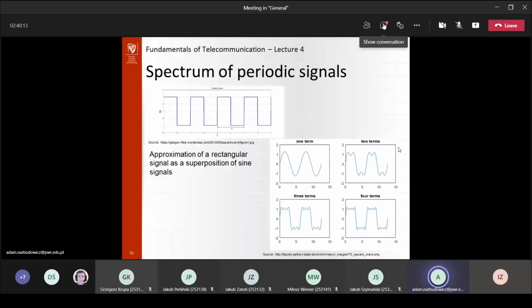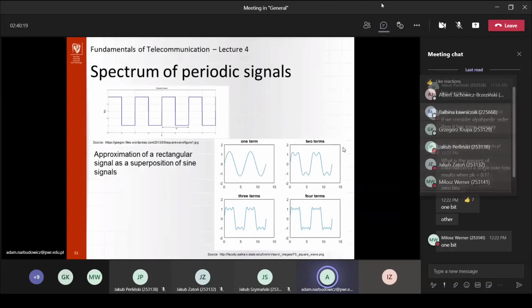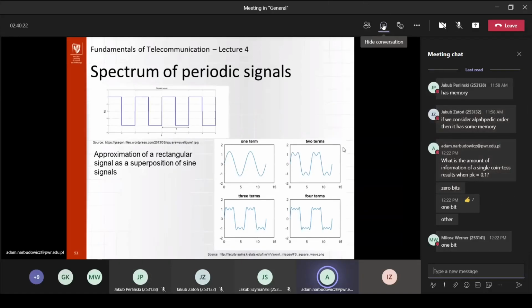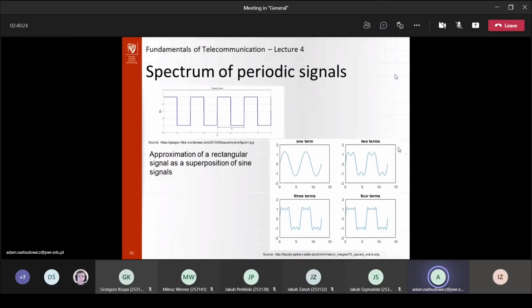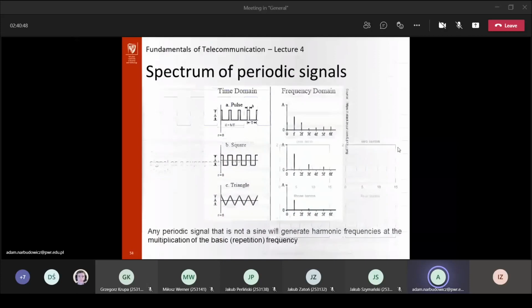There will be a filtration slope, right? Which means depending on how you design your device, certain signals can leak into your signal from the edges of the slope, right? And that's exactly the point where oversampling might sometimes also be beneficial. Simply, if you have a low order filter with not very steep slope, then you can combat that by adding a few more samples.